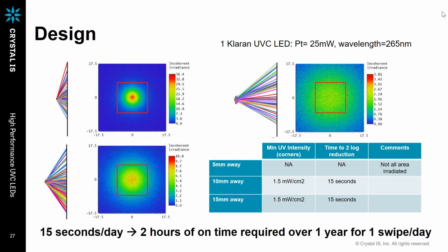There is a question related to safety. In terms of safety, in general, with a UV source you need to worry about the skin and the eyes. Overall, the UVC light will not penetrate through your skin. So typically, wearing some kind of safety glasses and gloves should be enough when working with the LEDs.